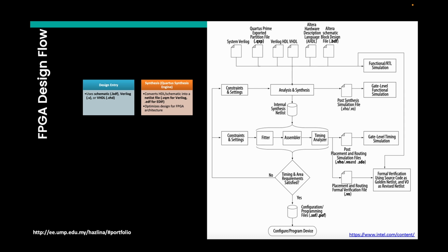In the logic synthesis stage, the HDL code is converted into a gate-level representation that can be implemented on the FPGA. Using tools like Quartus, we translate the Verilog code into actual logic gates. For example, the system ensures that the LED module is correctly mapped onto the FPGA resources like the logic elements and flip-flops.